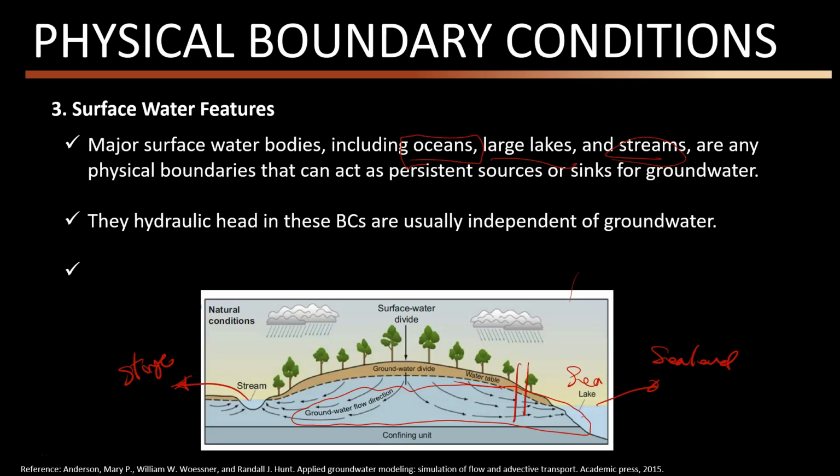For example, I know that if I put 10 pumping wells here, it doesn't matter how hard I'm pumping, it is almost impossible to change the sea level, right? So this is why we usually like surface water bodies to be at the border or at the boundary conditions of our conceptual model or numerical model.